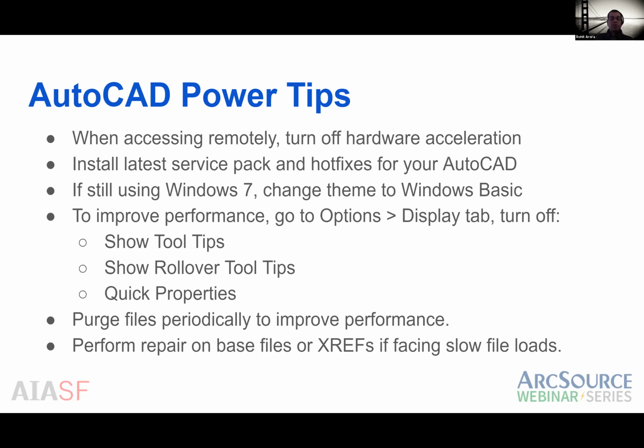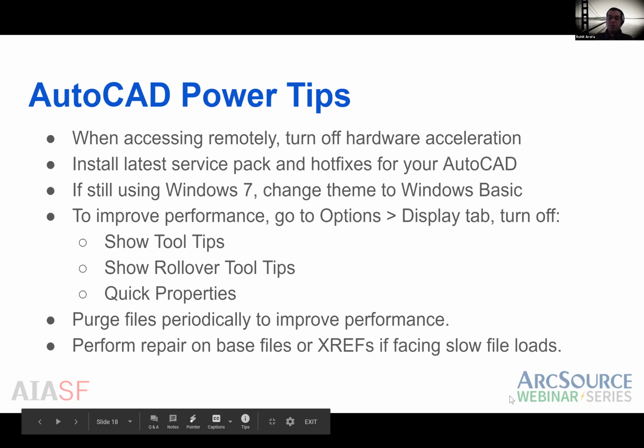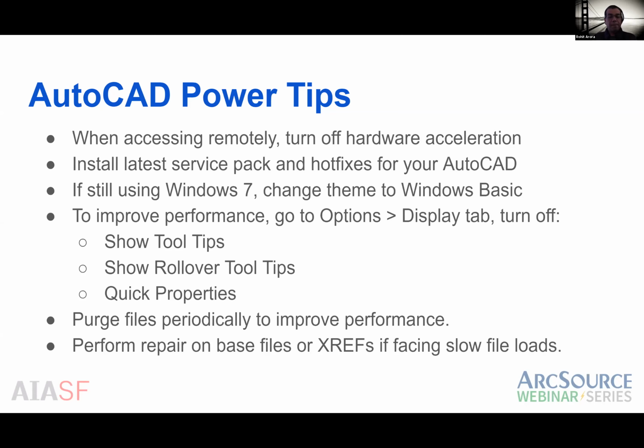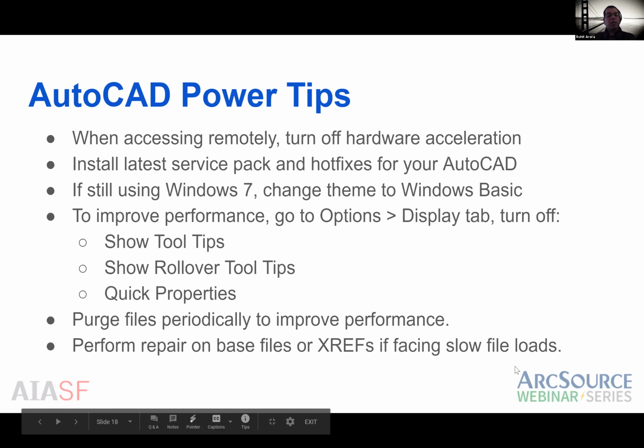Then purge your files periodically. That includes the XREFs. So if you feel that over a period of time your file performance has gone down, take a look at the XREFs as well as the main base file. And if you feel, even after purging, do a repair. There's an audit function. Try and do that.